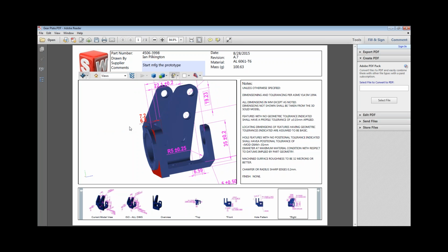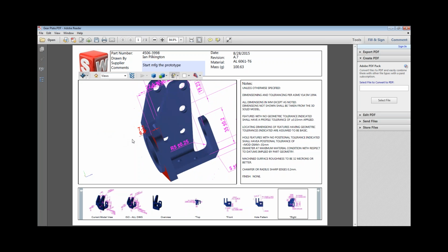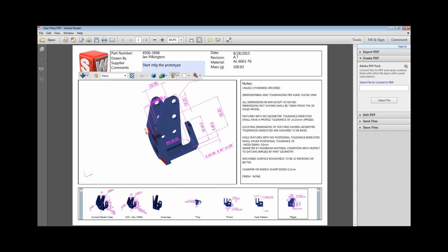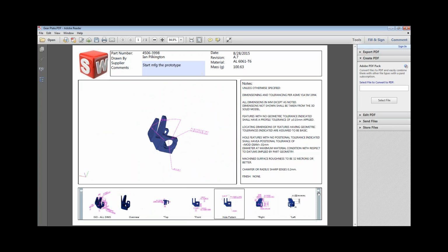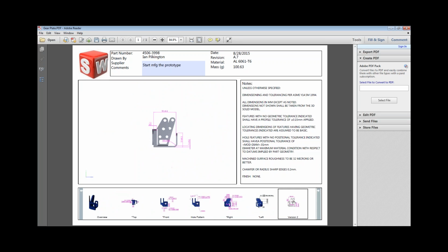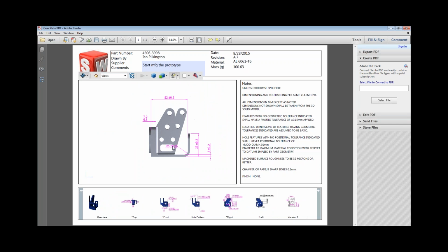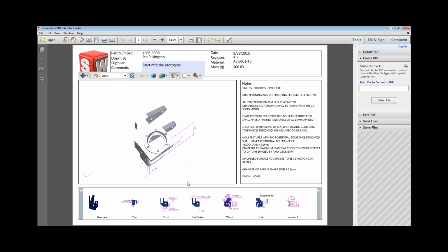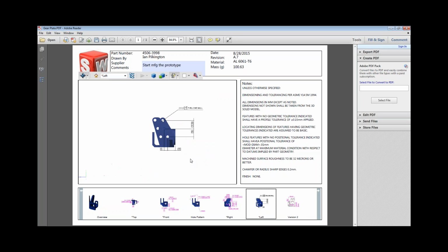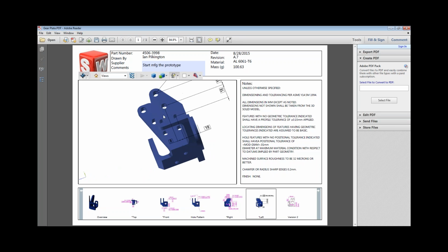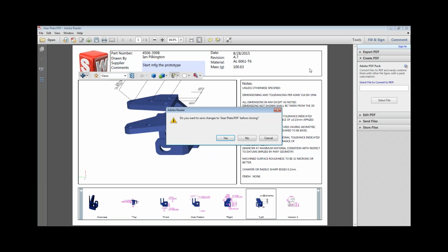So it's a good way of looking at it rather than looking at a 2D drawing, which is very difficult to interpret sometimes. This is the best way you can make use of SolidWorks MBD if you're planning to make your office a paperless drawing office. You can see all the views are placed there. Just browse. This is a configuration that we used, and you can rotate it in 3D. Again, you can have all the options which are there in 3D PDFs available here. So that's a great way of looking at it as a 3D PDF, right? Everything is 3D.